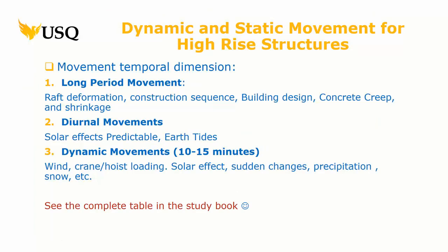You have concrete creep, which I said before, concrete shrinkage. Then the long-term effect, concrete can actually creep. It can change its shape, right? The recent disaster in Italy, you know, it seems to be that's what they're focused on. What's happened to the concrete that was encasing the columns in that bridge? You know, did it just deteriorate? Did it move? Right? So concrete creep is a real issue. The building design can be such that it actually affects the long-term effect, right? I mean, that's a factor that's outside your control, but you may be involved with monitoring it.